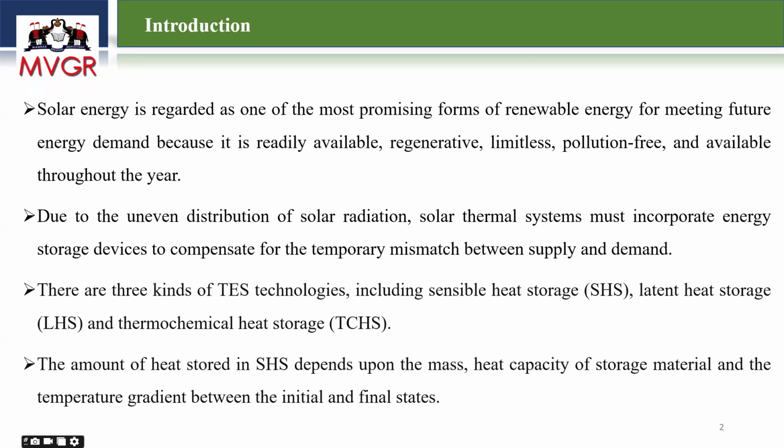For example, let us take 1 kg of ice, with an initial temperature of minus 20 degrees. You give that ice some heat, it starts rising in temperature and reaches 0 degrees. Once it reaches 0 degrees, the ice keeps on absorbing heat, but at isothermal condition. It is changing its phase, but the temperature is not changing. Once it has completely converted from solid to liquid, only then does the temperature start rising.